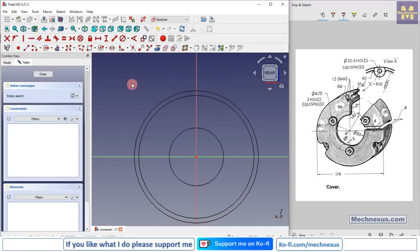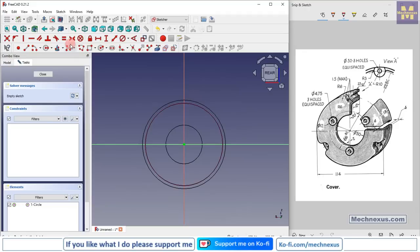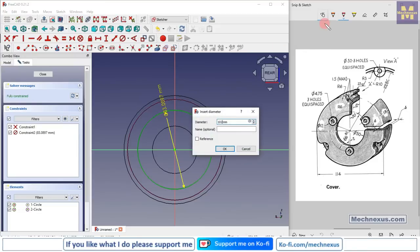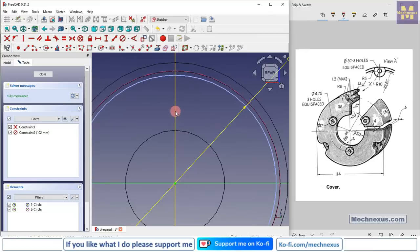Select it and switch to the wireframe, click on project geometry and project this, and we will select a circle tool, create a circle, and select diameter and provide a dimension of 102, and we will select it and make it construction, and here